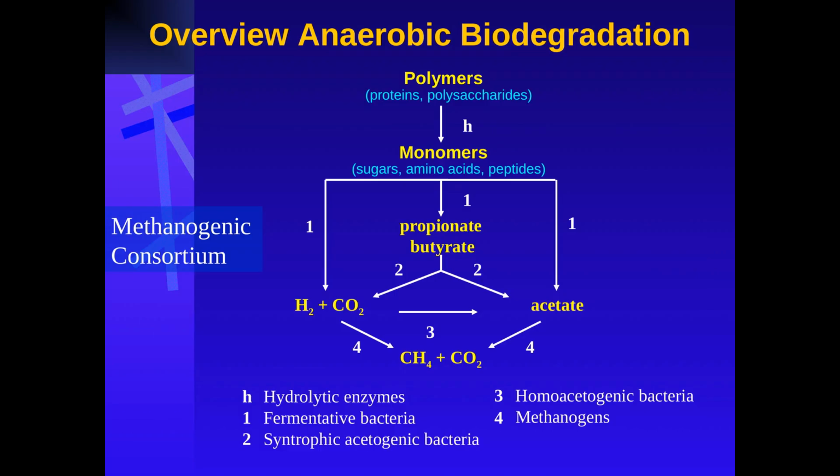High-rate anaerobic systems are designed to retain a high concentration of biomass, which allows for high loading rates and short hydraulic retention times. This is achieved through various reactor configurations that promote the formation of granular sludge or the attachment of biomass to a carrier material. These systems are capable of treating large volumes of wastewater in a relatively small footprint.